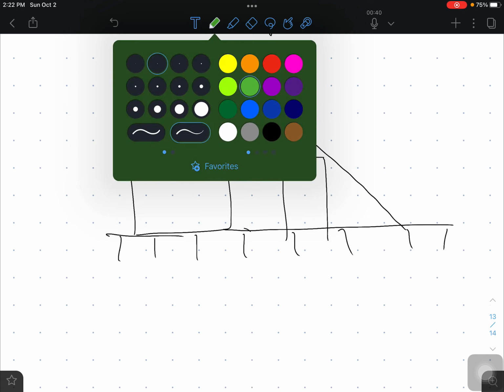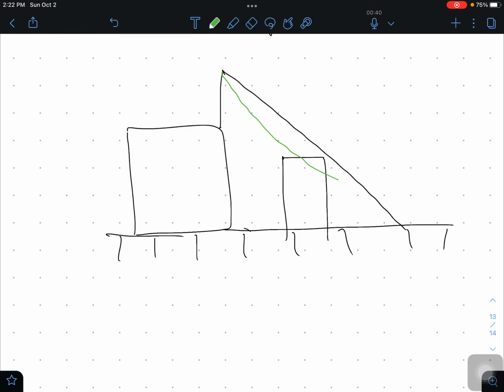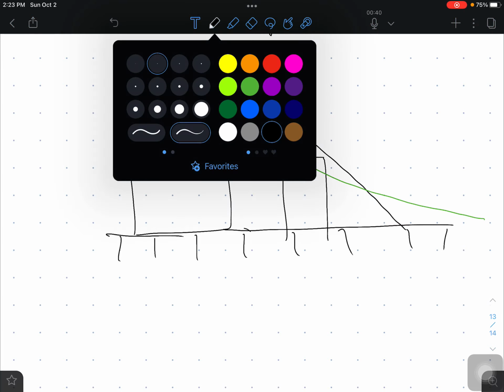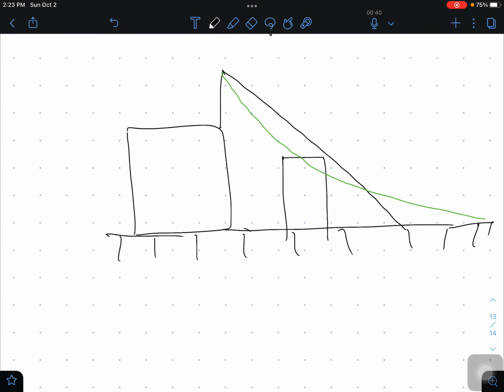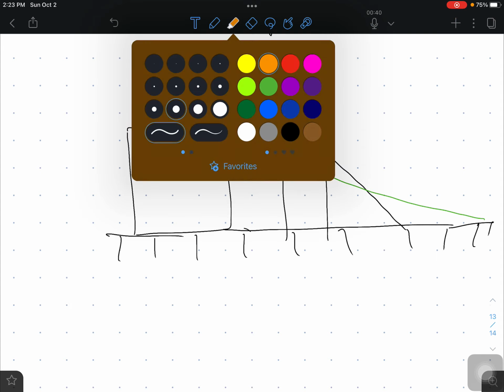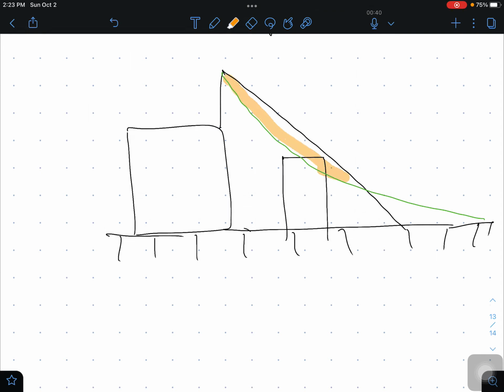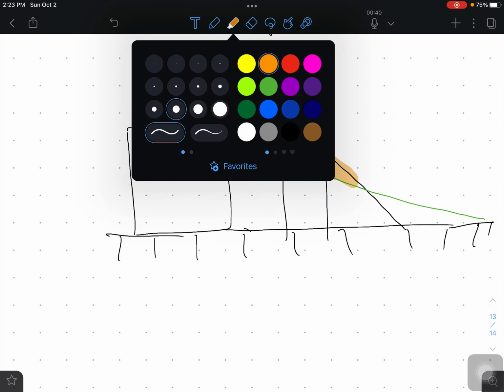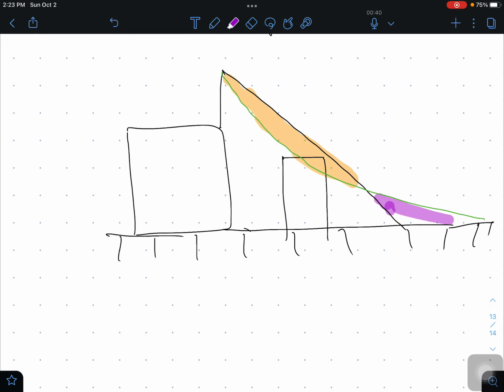Whereas through rolling sphere we are unable to protect this equipment. So now you have understood the difference between both the methods. This part offered by protection angle is called the overestimated part, and this part which rolling sphere is offering and protection angle is not offering is called the underestimated part, and both areas A1 and A2 shall be equal in order to decide the protection angle. This is what we studied in the first lecture.